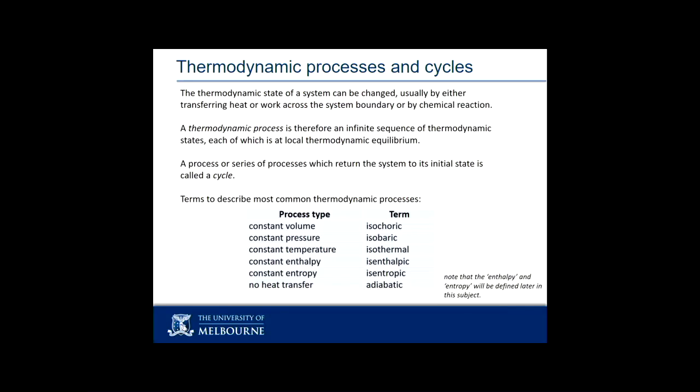That's important because when we're analysing energy transfer, we need to keep track of all the different ways that energy can change. One of them is by heat transfer. And if I tell you it's adiabatic, I can cross that term out and it becomes 0. If I tell you there's no change in the system energy, I can cross out the work term. So we're going to learn lots of different tips and tricks about terms that I can cross out and when I can cross them out. And it's connected with the maths of the processes that we're dealing with.